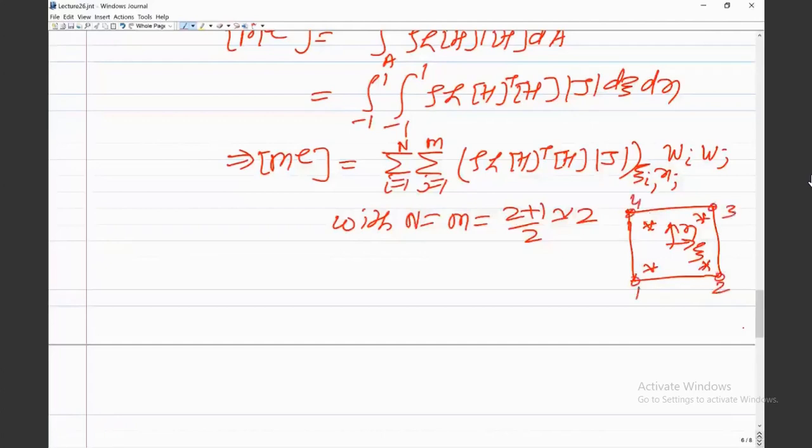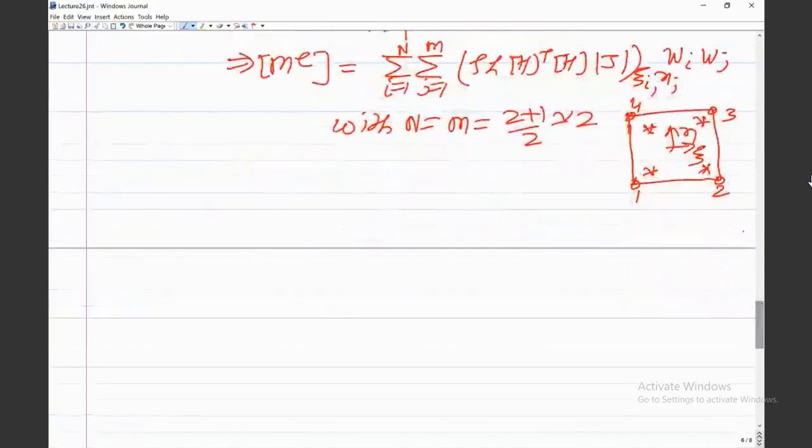So yeah, this is how you can write the mass matrix for this. Of course, you will have to evaluate it numerically through the numerical integration. Because the element is arbitrary quadrilateral, so you have to do the numerical integration, because explicit integration will not be possible. So then for one more element, let me also demonstrate to you the mass matrix for one plate bending element. Now similarly you can do for others, so I'm just taking one example. So the next is mass matrix.